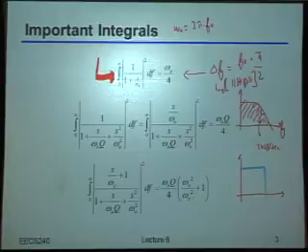Yeah, exactly. There's still actually a lot of noise that you're integrating after that cutoff frequency. And in particular, for a first-order low-pass filter, the kind of roll-off there is lazy, right? Meaning it's not rolling off very quickly, so there's still a reasonable amount of energy you pick up from integrating out in that frequency region. Okay?